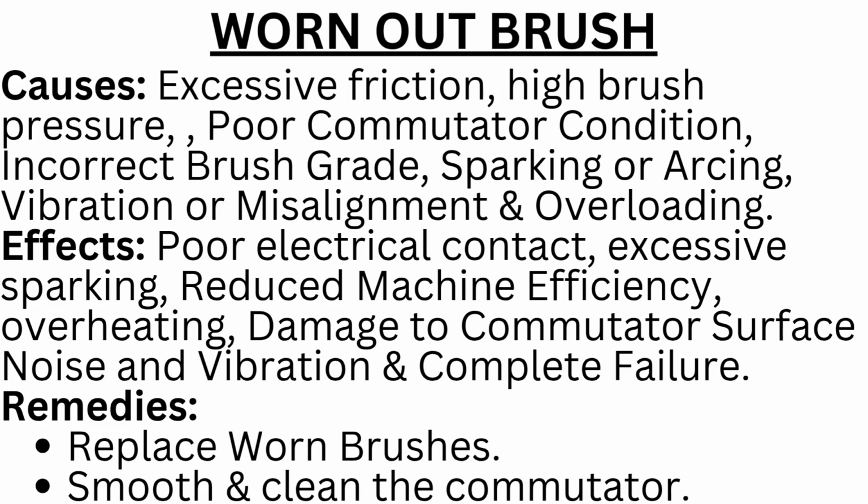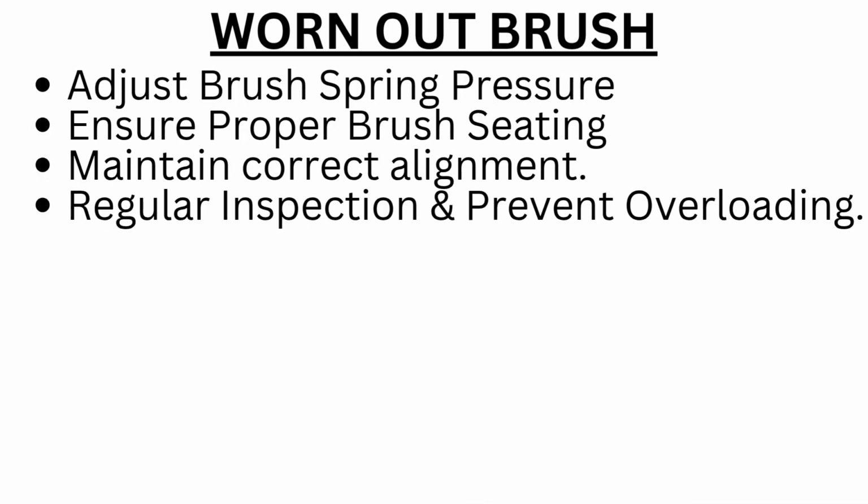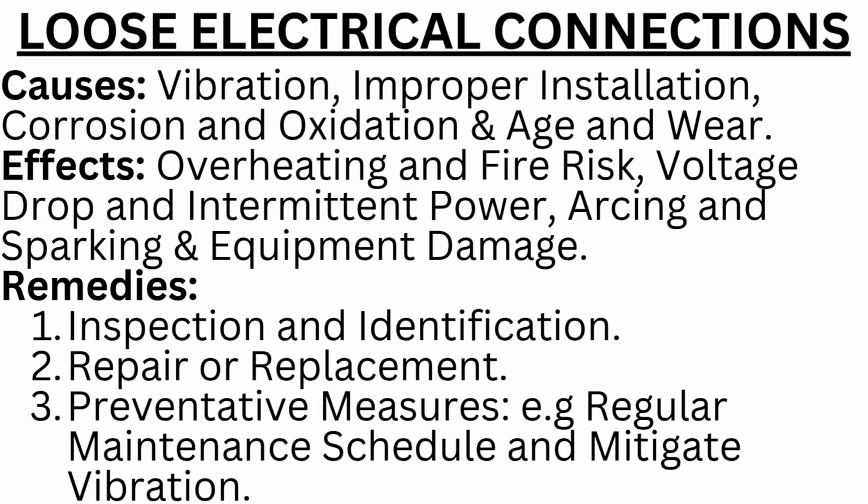Remedies. Replace worn brushes. Smooth and clean the commutator. Adjust brush spring pressure. Ensure proper brush seating. Maintain correct alignment. Regular inspection and prevent overloading. Let us look at the next maintenance failure, loose electrical connections.